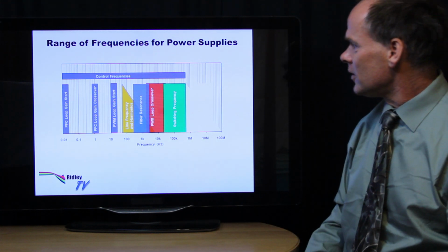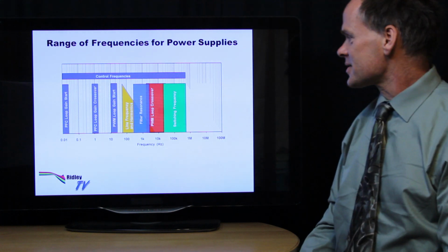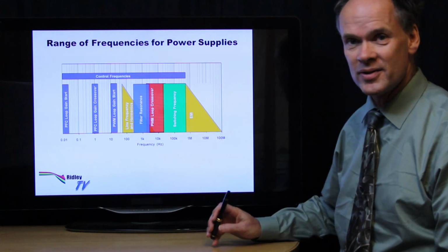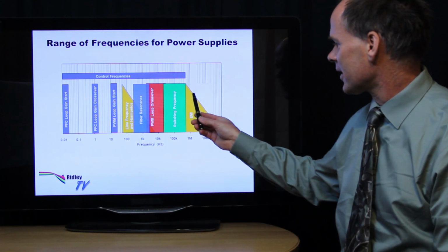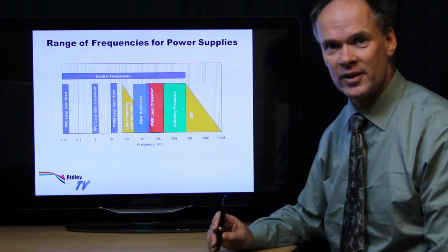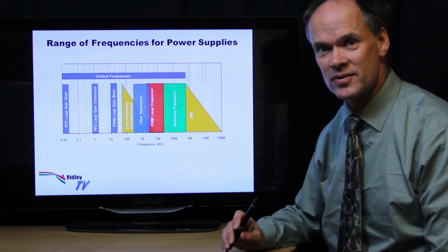That's our control, and going beyond that we're going to see more things happening because we see EMI due to the switching frequency of the power supply, and it will kick up harmonics really as high as you want to go measure them, 100 megahertz or into the multi-gigahertz range if you want to do radiated noise of switching power supplies.